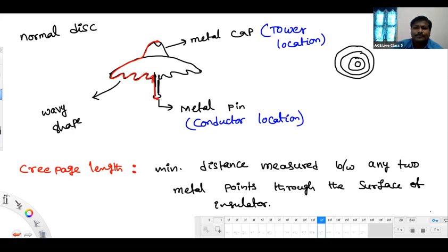Okay, sir. Sir, in HV lines, we are using straight insulators, many of silver type, no, sir. Is it the same as our porcelain one? No, wherever you find silver color, where you are using. In some low distribution sets, I saw 5 small shells, sir. Big or small size? Small, sir. That is a steatite insulator, not porcelain.